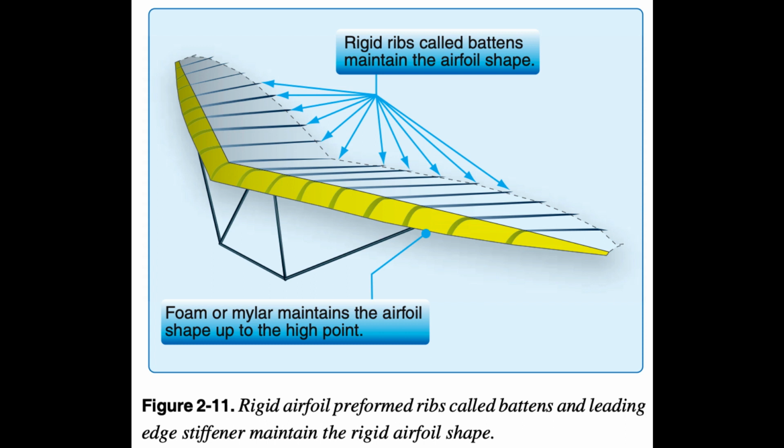Even though the airfoil sections are rigid, the WSC aircraft is called a flex wing for two reasons. First, it is designed so the outboard leading edges flex up and back when loaded. The flexing of the outboard section of the wing also allows load relief because the tips increase twist and decrease AOA. The greater the weight, the greater the flex in wing twist. This flexing allows the WSC aircraft to automatically reduce loads in unstable air, providing a smoother ride than a rigid wing. Since the wing flexes and reduces the load for a given angle of attack at the root chord, WSC aircraft cannot obtain loads as high as those obtained by a rigid wing. This flexing of the outboard leading edges also assists in initiating a turn.